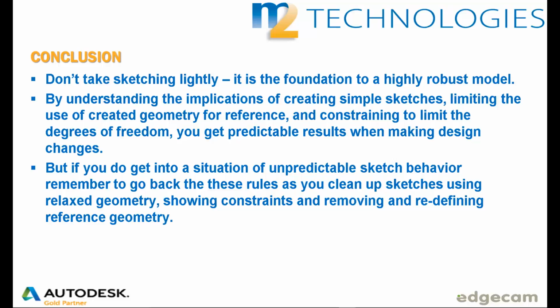Always start, after creating your geometry, by adding geometric constraints, as this defines your design intent, or how the model will behave as different sizes are applied to it. Follow that up by placing dimensions on the sketch to define its overall size. But remember, when you're creating those dimensions, please try to dimension from either a base feature or use some of the origin work points or axes, the 0, 0, 0, if you will.